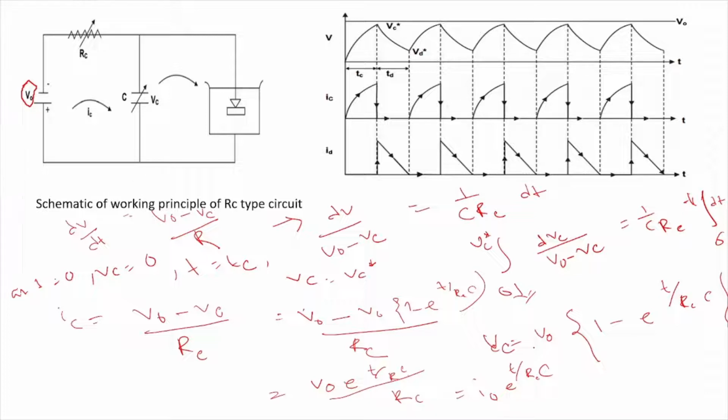Those formulas will be important for solving the numericals at a later stage, as we'll see. During the charging, the electrical load coming from the EDM may be assumed to be totally resistive, and is characterized by the machine resistance, which is denoted by Rm. Then the discharging current can be derived in terms of that equation as Id, denoted as the discharging current.